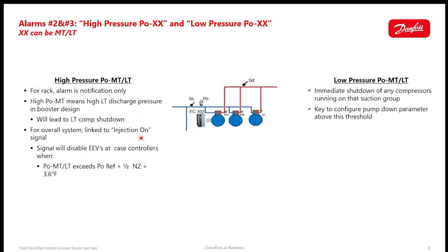For high suction, the alarm itself is just a notification. The pack controller is already trying to run all the compressors that are available that aren't already locked out to bring the suction pressure back down. So there's really no additional action to take directly at the rack.